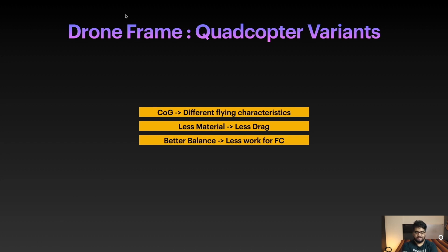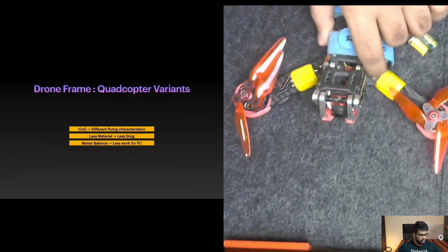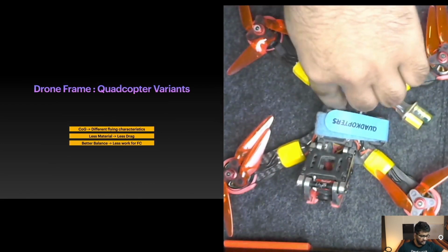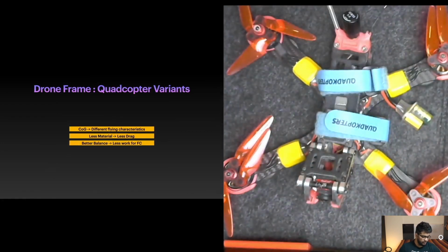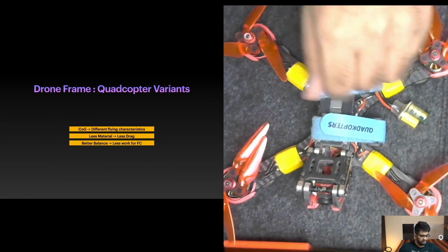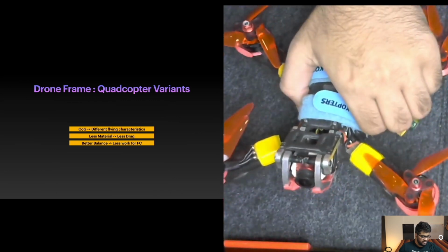Let's say I move to the overhead camera to show you, this is your drone frame, and your center of gravity needs to be at the center, so all the motors are doing an equal part. But for some reason the frame manufacturer was incompetent and designed the frame such that the balance is at the back. So ideally your drone would always be flying tilted this way.